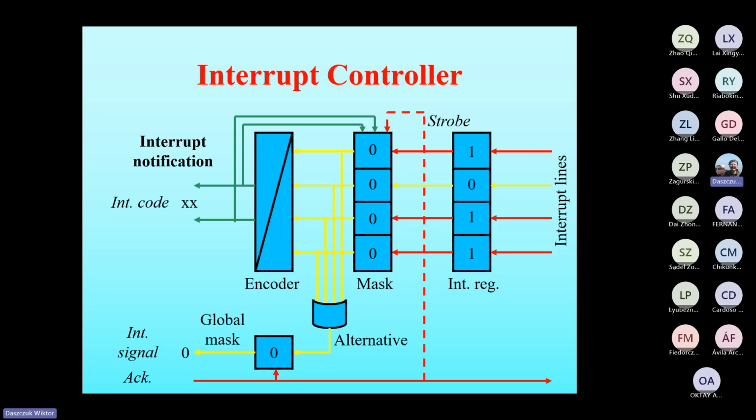After some time, a special command tells the interrupt controller that the given level of interrupt handling was finished, and it unblocks the mask and so on, but we will not deal with these details. Finally, if all interrupts are served, the mask should be all ones.